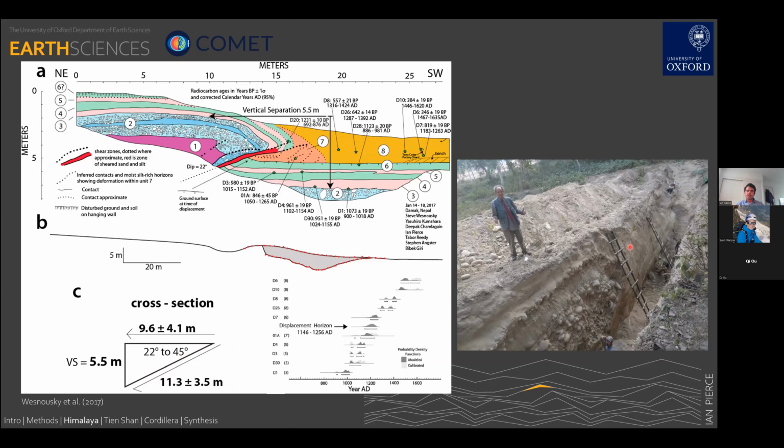By excavating a paleoseismic trench across the fault scarp, I can look for stratigraphic evidence of past surface ruptures. In this trench is a series of river sediments that have been folded and broken by a low-angle thrust fault. This is a fossilized earthquake. These folded and faulted sediments were originally horizontal and continuous. The earthquake broke these sediments and formed a fault scarp, not dissimilar to the photos I showed earlier. That fault scarp then eroded and sediments were deposited on the downthrust side of the fault.